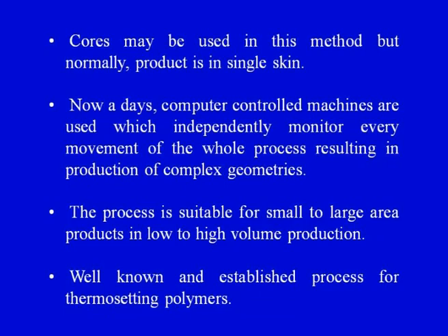in production of complex geometries. So, earlier when this process was developed, it was used for axisymmetric components, and the complex geometry of the axisymmetric components was sometimes a hindrance in the application of the filament winding process. But with the development of sophisticated computer numerical control machines, with the help of certain further design guidelines or design modifications which have been noted, and with the development of new materials which are used for making the mandrel, now this process can achieve fairly complex geometries.